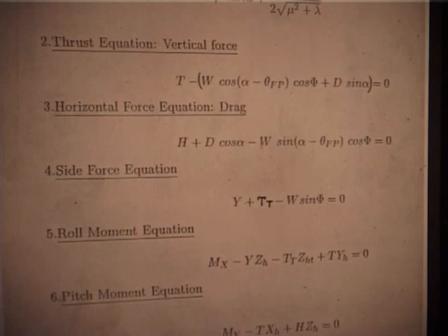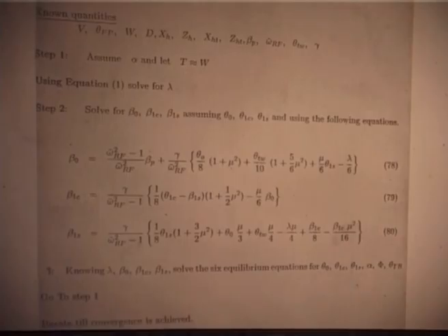That is why now you see your equilibrium, this part we will come to later. This aeroelastic problem is part of the trim problem, because you cannot decouple the aeroelastic problem in helicopters. Aeroelastic problem is the response of the blade to air loads, that will be sitting in between, okay, because you cannot just like that solve the equilibrium equation separately, because you must know the blade response.